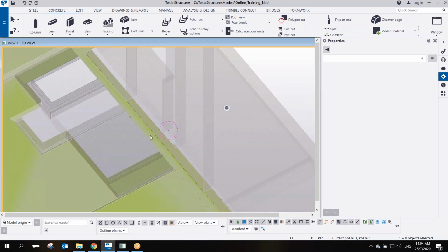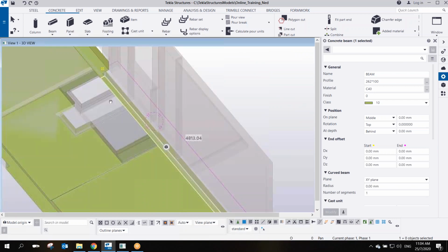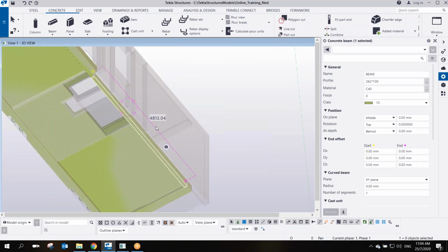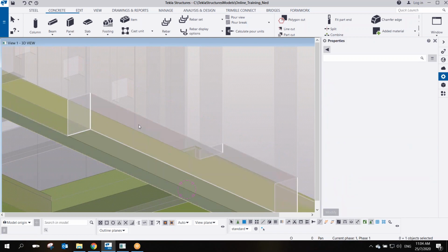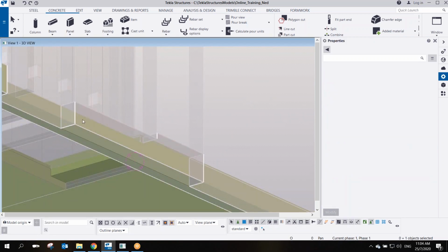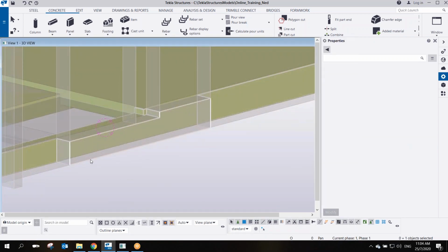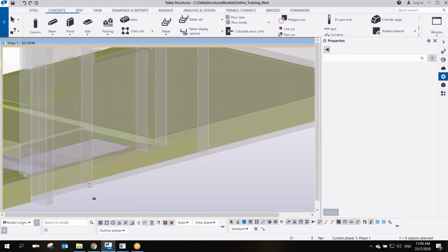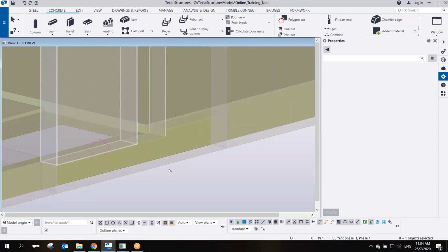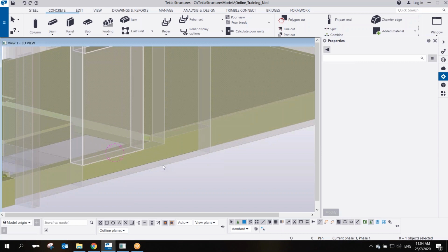So look, what I did is I made a straight beam here. And then here, if you notice, this one is a separate beam, but I did not consider this one as a beam, and I will put that one as part of my wall, from this wall, and this wall, and this wall. So that one will be one wall, so that I don't have too many cuts.